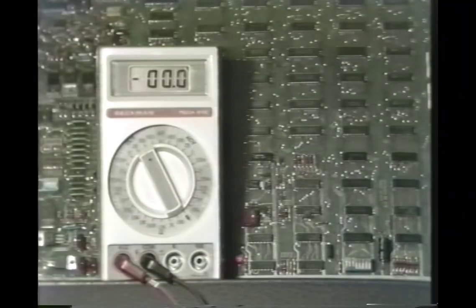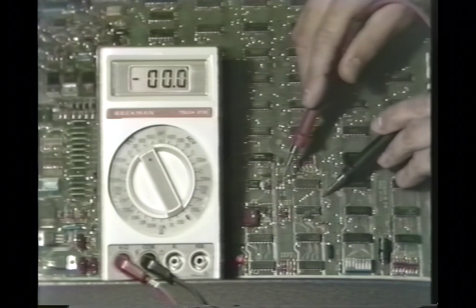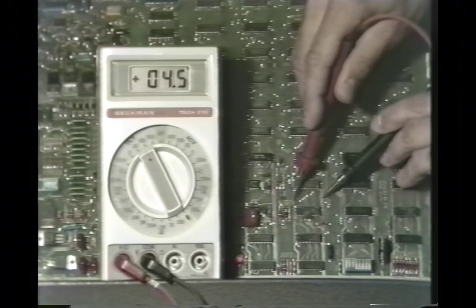Now let's see how the average mechanic might tackle this problem. Anytime you have bizarre problems with your game and you don't know where else to turn, start by checking the power supplies. Knowing that power supplies are responsible for a large percentage of the failures in games, our average mechanic checks the power supply across the power rails on the printed circuit board. But the meter doesn't read 5 volts.